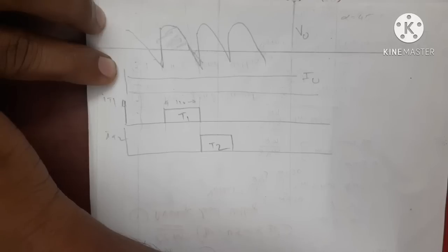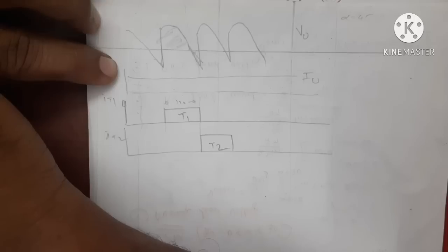But just imagine that if you are having more negative portion in the voltage waveform compared to the positive portion, then it will be working more as an inverter. I repeat, if you are having more negative portion than the positive portion of the voltage waveform, then the circuit is experiencing a power transfer from DC side to AC side. So it will be acting more as an inverter. Practically that will happen if you are having a DC voltage source at the secondary side with the reverse polarity. We will come to that portion later.